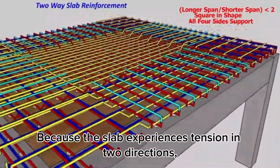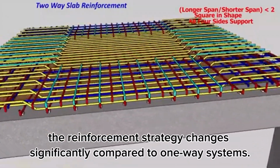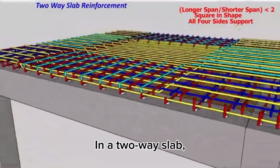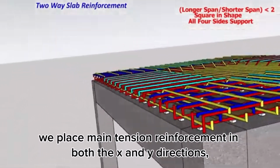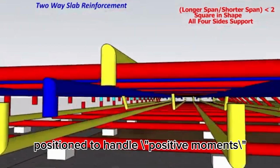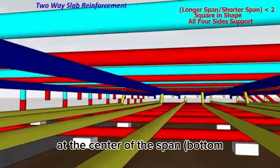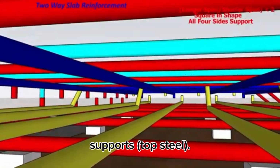Because the slab experiences tension in two directions, the reinforcement strategy changes significantly compared to one-way systems. In a two-way slab, we place main tension reinforcement in both the X and Y directions, creating a dense mesh. This mesh must be carefully positioned to handle positive moments at the center of the span, bottom steel, and negative moments over the supports, top steel.